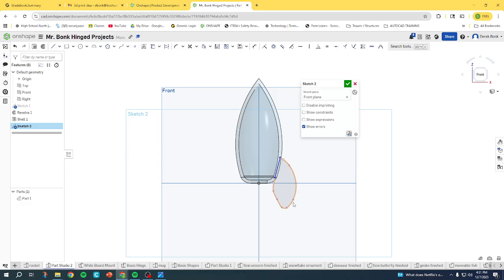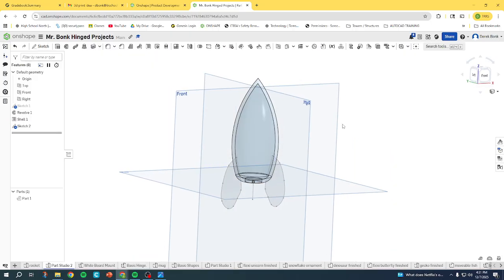You can also, now at this point, if you have escape and the white arrow selected, you can grab this shape and you can sculpt using the points, using the lines, however you want. You're going to put a line, just has to be anywhere in the middle, something like that. Hit escape to finish it, because you're going to use that to mirror, which is this tool here, mirror. You're going to select the mirror line, and then the objects you're going to mirror, which is the spline and that. And boom, you're done with your fin sketch.